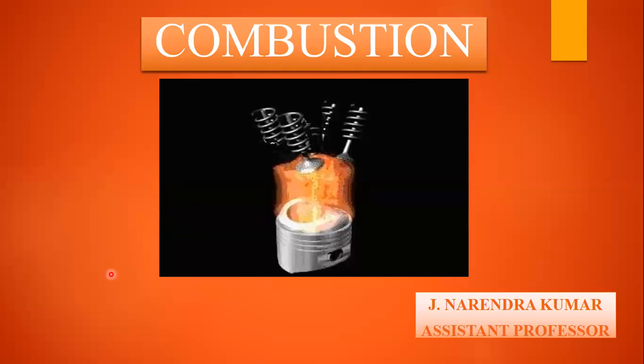Because theoretically, what we have discussed till now, the combustion happens exactly at the top dead center. But in actual cycles, it is not going to be exactly at the top dead center. We need to advance the spark. During the time loss factors I have discussed this with you. We are going to have progressive combustion in the case of actual engines, so we have a time loss factor, and because of this we are going to have an effect on the combustion process.